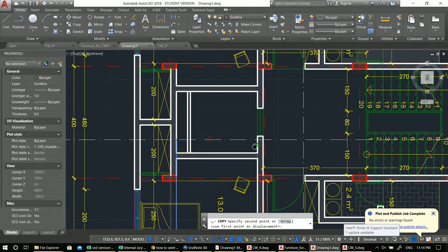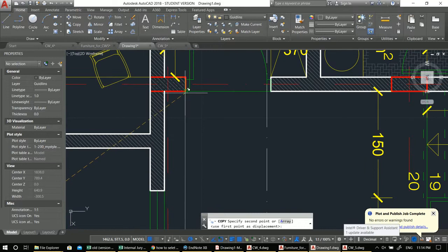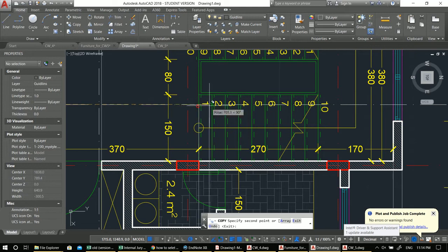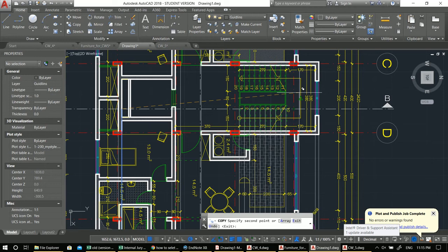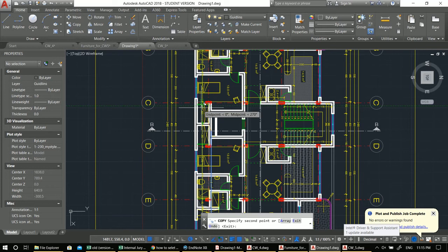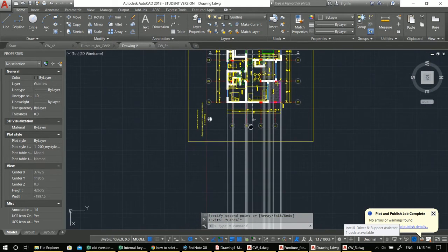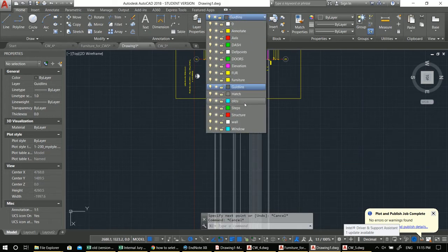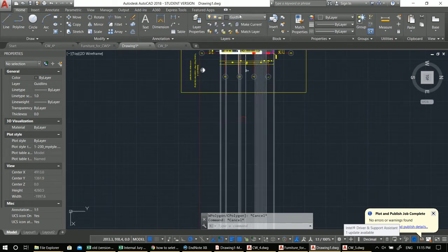Okay, so basically let's find this. We have the door here, very good, and then we have the steps. Sorry about that, we cut the steps actually, but because there are too many of them, let's keep it as is. Okay, now nothing else. If your structure is exposed, you can go ahead and add your exposed structure. After I'm done finishing these lines, I'll come here and draw my ground line. If you have specific topography, go ahead and put the topography, but make sure that you are going into the proper layer, usually the layer wall.